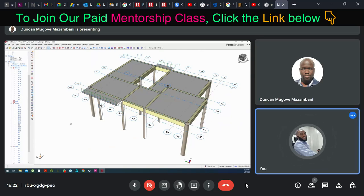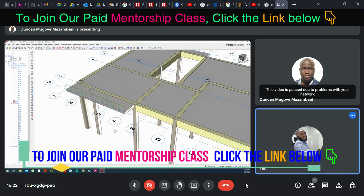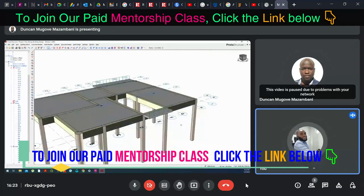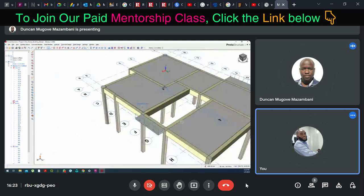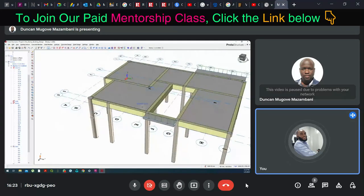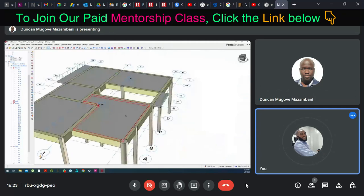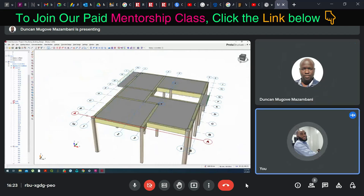Okay, that's fine now. So you can now see how the load is, right? Zoom in, and then rotate. You can now see your cantilever load. Cantilever load. Okay, that's fine. So right now we have inserted our slab, column, beam, and cantilever slab. So now it's time to go and insert our story. So go back to your plan view.